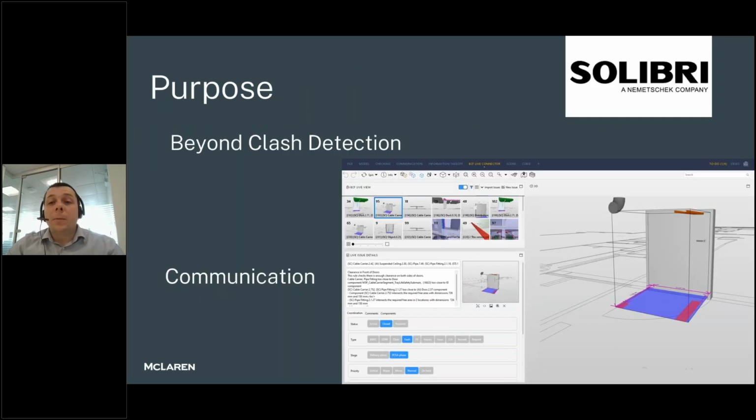We chose Solibri because we have inspirations to do things which are beyond clash detection. We like calling it design validation. And apparently the model elements are not just some dummy objects, but they are defined by their function, which we can use to check against the Solibri predefined rules. For example, this door, which the software recognized the opening direction and recognizing the clashes and visualizing them.